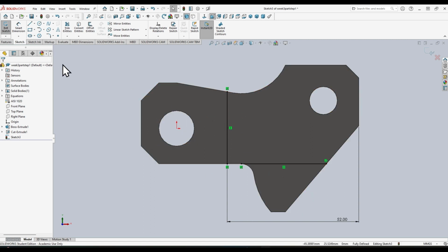I don't know if you guys remember the button that we use, but we can click on this surface and hit Convert Entities, and it sketches everything out for us. I actually have all this drawn too, but I'm just going to leave that on there because I'm lazy, and I don't really have to delete it because I'm just trying to complete this. What I want to utilize is the part of the sketch that's over here. I think I also need to convert this entity, so I'm going to click on that separately and then hit Convert Entity just to make sure that one got sketched as well. So it looks like all my sketches exist the way that I want them.